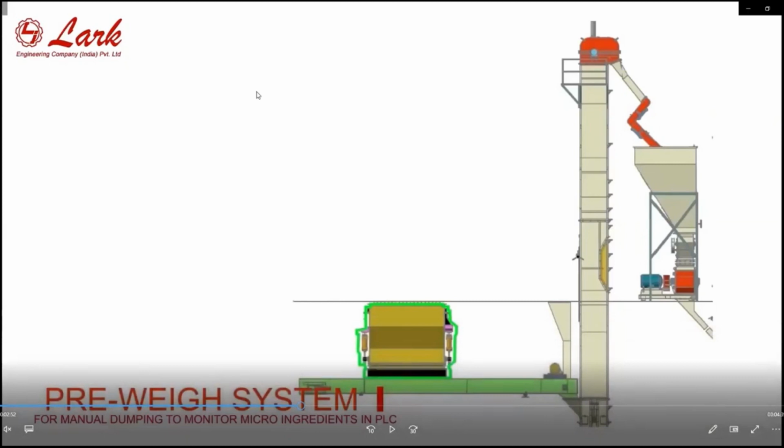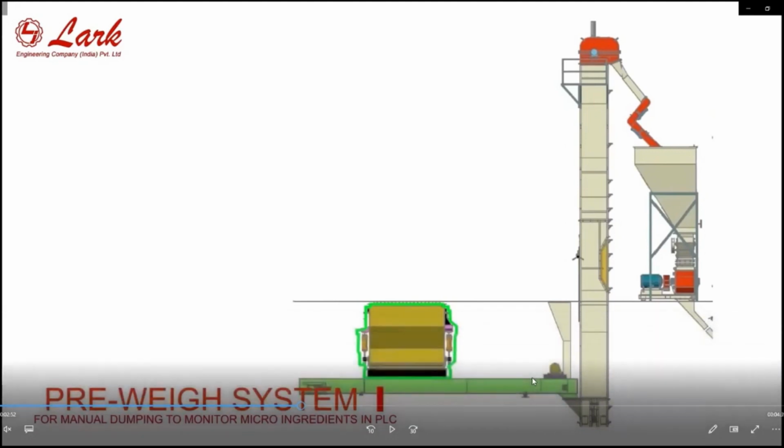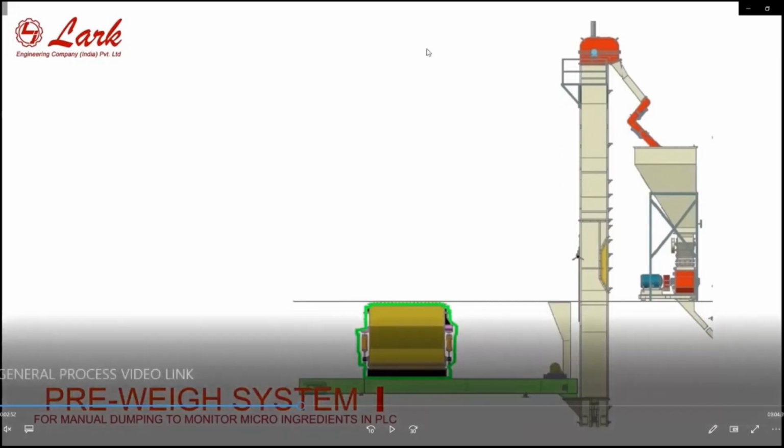You do not want to fill the batching bin with ingredients that do not have good flowability properties, like cotton seed cakes and the other cakes in cattle feed, and fibrous material. We have to add those manually through the grinder elevator. But in that manual process, we have no idea whether our operator skips the material, or puts it into the grinder elevator in the right sequence.